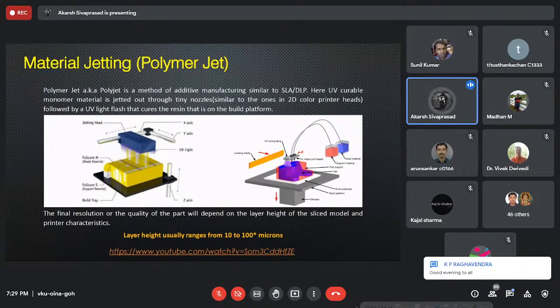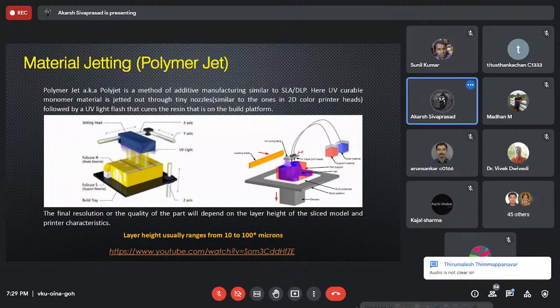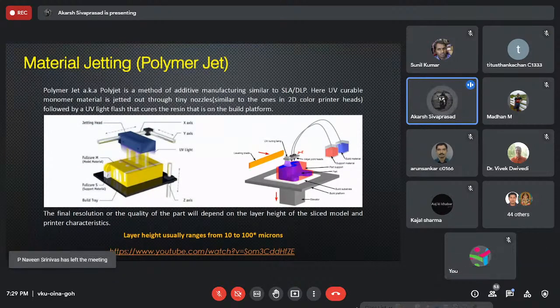One drawback for this technology is you definitely need 100% density support below it, so that when your next layer starts jetting droplets, it has some base or rigid substrate to fall on and cross-link when the UV shines on it. So this technology needs 100% supports under all the overhangs.